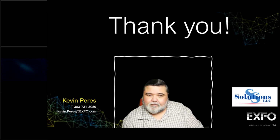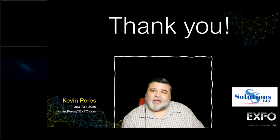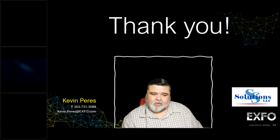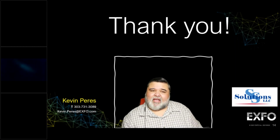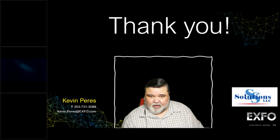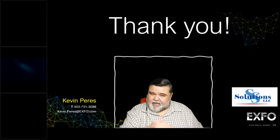Oh, so realistically, you're saying that you start over at 0 after the split or the tap, and then it's 90%. Well, you don't start at 0. So let's say that coming into the first 90 by 10, for easy math, you lose 1 dB. So you go from 0 dBm to -1 dBm. And so when you arrive at the next tap, you arrive at -1 dBm. It's going to take 90% of that -1 dBm and pass it along. It's just taking a percentage of what arrives. And so the power keeps going down and down and down.